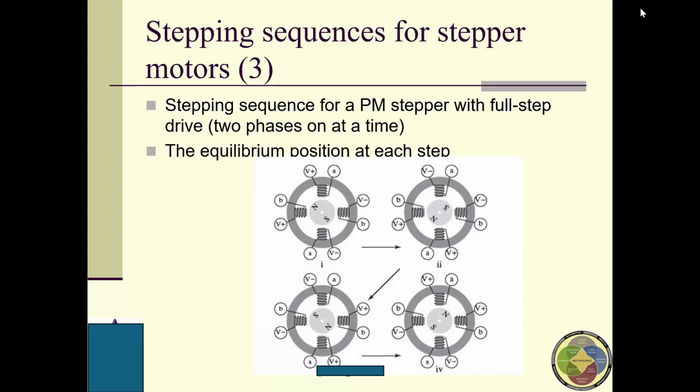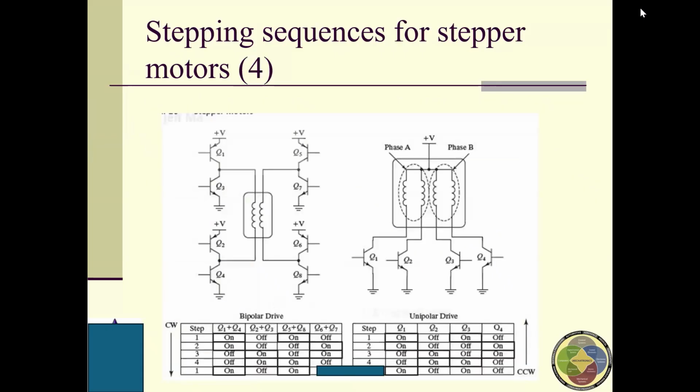So this is our second mode. 2 phases are energized at one time. So this is for 2 phases and how we sequence for the full step drive. This is the bipolar drive and the unipolar drive. The same thing you can see.